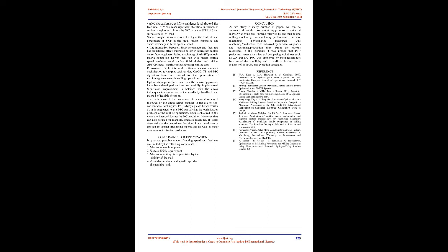using a carbide tool. Also in this work, different non-conventional optimization techniques such as GA, ACO, TS, and PSO algorithms have been studied for the optimization of machining parameters in milling operations. Optimization procedures based on the above approaches have been developed and successfully implemented. Significant improvement is obtained with the above techniques in comparison to the results by handbook and method of feasible direction. This is because of the limitations of enumerative search followed by the direct search method. In the use of non-conventional techniques, PSO always yields better results. So it is suggested to use PSO for solving the optimization problem of milling operations.